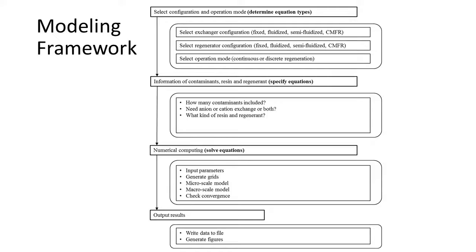Trevor, on the iron, to keep moving on here, when you say fouling, my mind's thinking about what species and forms are involved, what's going on. Presuming the groundwater, it's Fe2 dissolved originally. They're oxidizing it, making oxidized iron. But a bunch of that iron, some Fe2 or Fe3, is complexed with the organic matter, and you get particles settling out. So what's going on in your ion exchange columns is complex. What wants to interact with your ion exchange media?